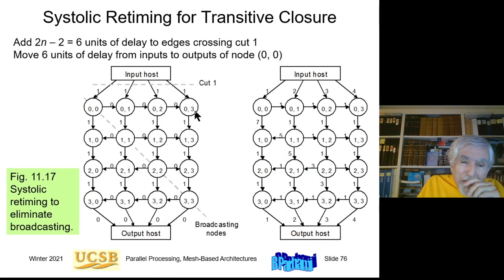Okay. So the solution that I did not describe to you, the timing is like this. So there are these broadcasts. See, this cell broadcasts to the entire row. The next row, this cell broadcasts to the entire row. And the next one, this one broadcasts. And then by retiming, basically this 0 is changed to 1. So this signal comes into this cell 1 time unit later than this original implementation. So I delay this input also by 1. So these two now arrive at the same time.